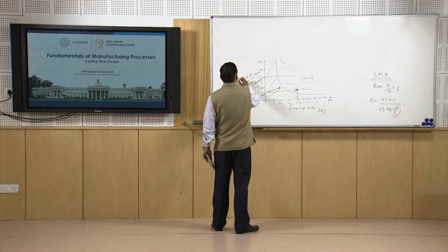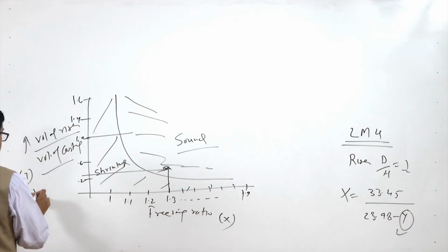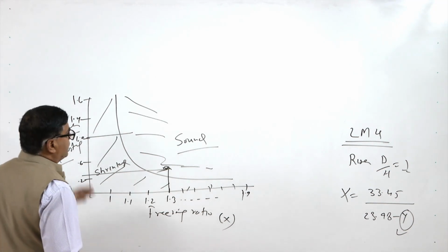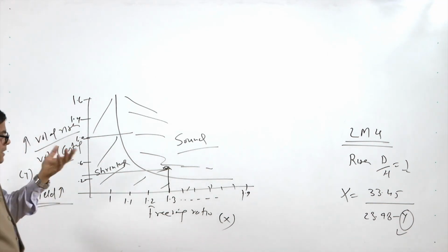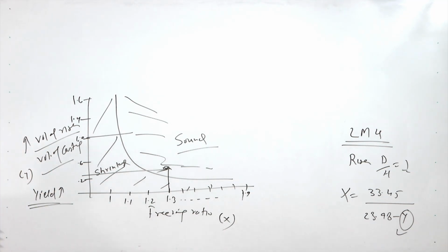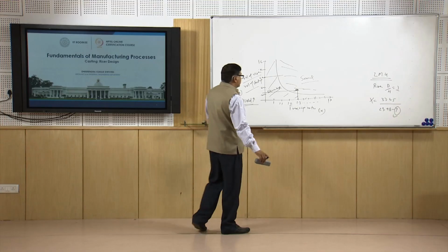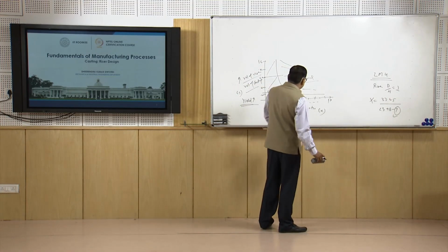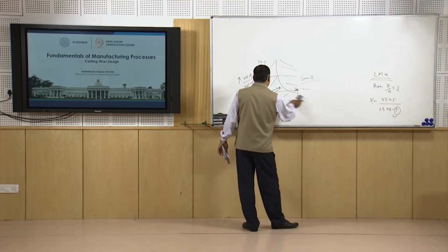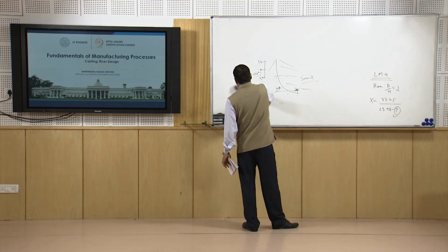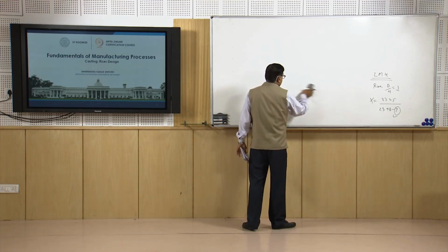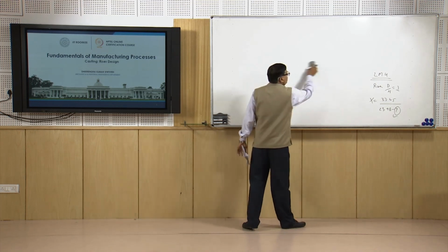So, if this ratio is high for sound casting, then definitely our yield will be much better, because the molten metal being solidified in the riser will be less as compared to the volume of the metal which is solidifying in the casting. So, efforts are always made to have better freezing ratios for achieving the high yield through a low riser volume to casting volume ratio.